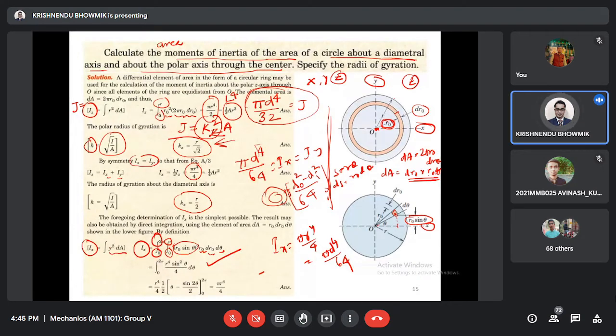When it is an axial member, the cross sectional area, that is, the size, is important. But when it is bending or torsion, both size and shape matter. Shape means Z sections, I sections, L sections, C sections. Many times in aircraft components you can have different cross sections. In civil structures you can see channel sections. In metallurgy and mining you can have L shaped cross sections.